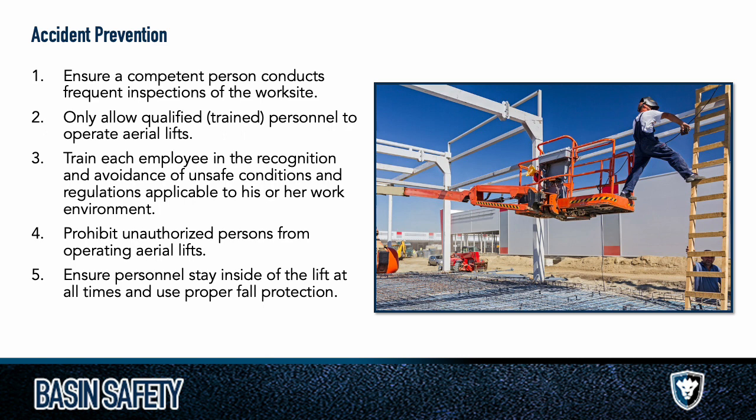So you've got to be trained and qualified to operate the equipment. Each person needs to understand what unsafe conditions exist while operating an aerial lift, which we're going to cover today. We want to prohibit unauthorized persons from operating aerial lifts, and then also make sure people stay inside of the lift once they're in the lift, unless they're moving to a platform and they have adequate tie-off. As in this photo, which is not following those rules.